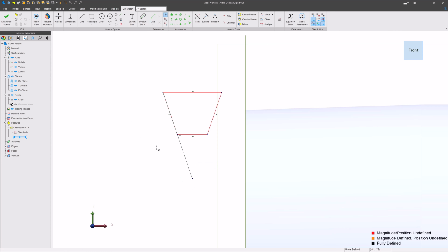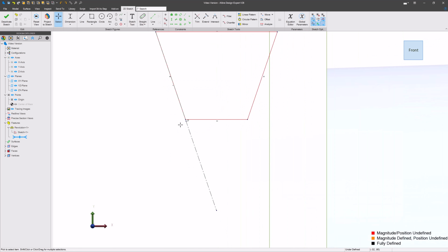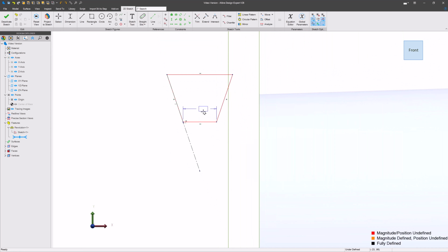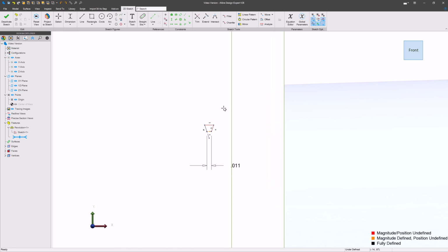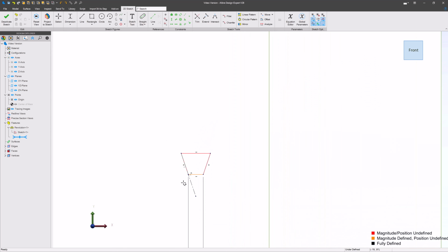And then if you're in Pro and Expert, just put a point down. If you're in Atom, just use the point off of a construction line. And we'll make a midline constraint and make our point just in the middle, right? Makes a nice little marker of that. Now, the horizontal distance of this should be pitch divided by 8. And you can see that resizes pretty substantially. And then there's our midline, right?